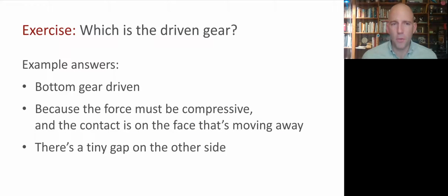Well, if we think about it, we can see that the bottom gear is going to be driven. And that is because the force has to be compressive. You can't have a sort of tensile contact force between the teeth. And the contact is on the face that's moving away from the driving gear. And you can also see this because there's a tiny gap on the other side. So the top gear in this case is driving the bottom gear.